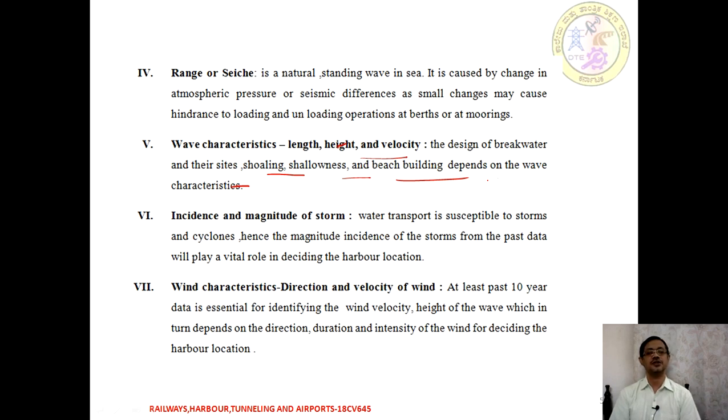Similarly, the wind direction and wind characteristics with respect to velocity are also going to be important. As we know, 10 years of data is important in identifying its velocity and height of the wave, which in turn depend upon the direction, duration and intensity of the wind. So it is going to be decided for proper direction and location of a harbour.